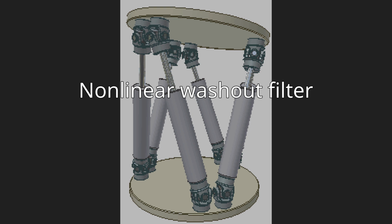For example, the algorithm described by Daniel and Augusto computes a gain A as a function of the system states, thus the washout is time varying. The gain will increase as the platform states increase their magnitude, making room for a faster control action to quickly wash out the platform to its original position. The opposite outcome occurs when the magnitude of the platform states is small or decreasing, prolonging the motion cues, which will be sustained for longer durations.